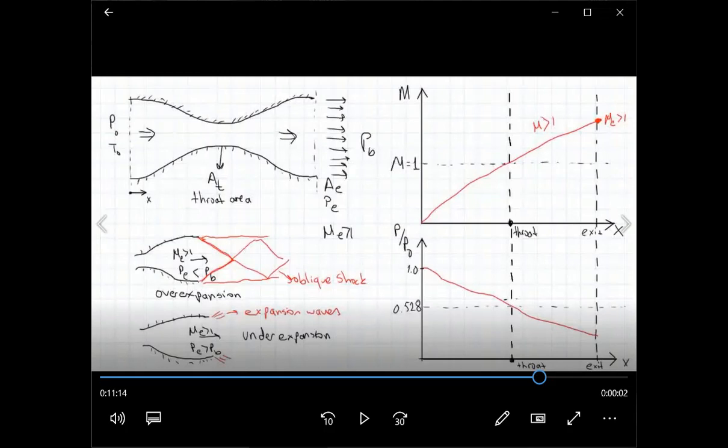The first term is related to the inlet and exit velocity difference times mass flow rate. But we do have a second term. The second term in the thrust equation for a propulsion system is related to exit area times the exit pressure minus atmospheric pressure difference. That difference may, in some situations, contribute towards a reduction in your thrust levels.